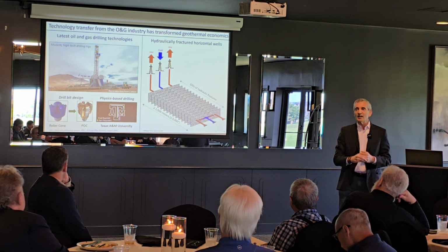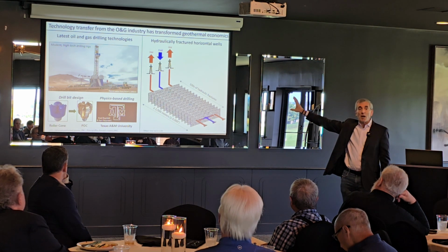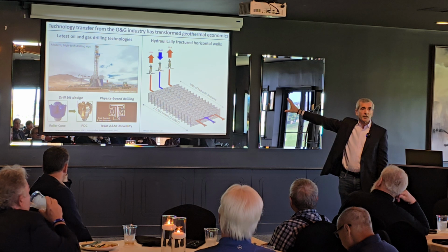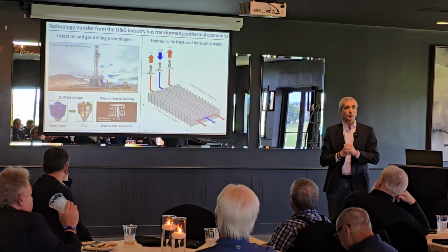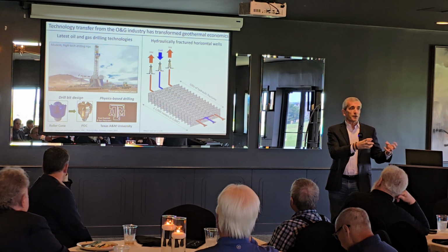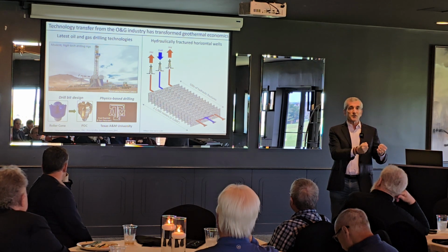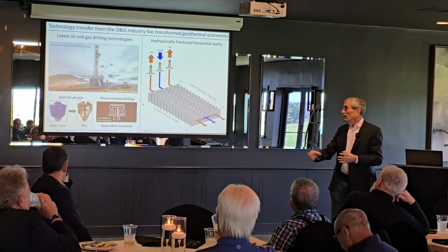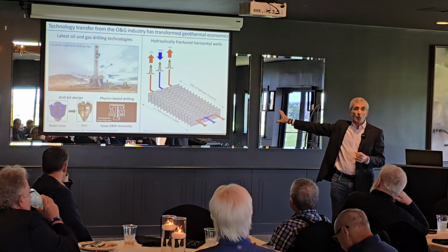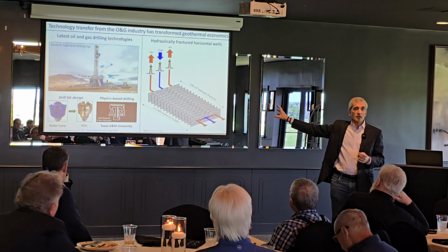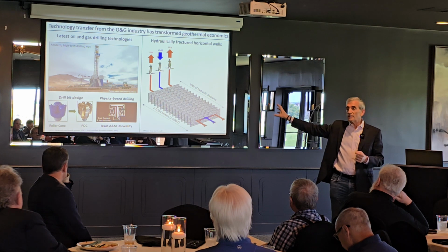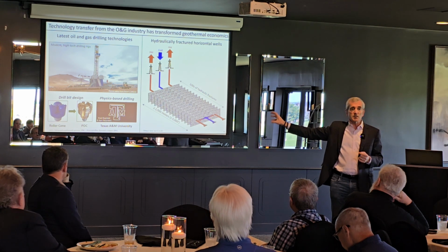It really was record-setting. But it was taking the modern drill rigs that we have in the oil and gas industry and putting them into the geothermal space, whereas the rigs being used previously, frankly, weren't that sophisticated and not that capable. It's using PDC bits instead of roller cone bits. I mean, we haven't used roller cone bits in most oil and gas applications in America for a long time. PDC is a lot better.